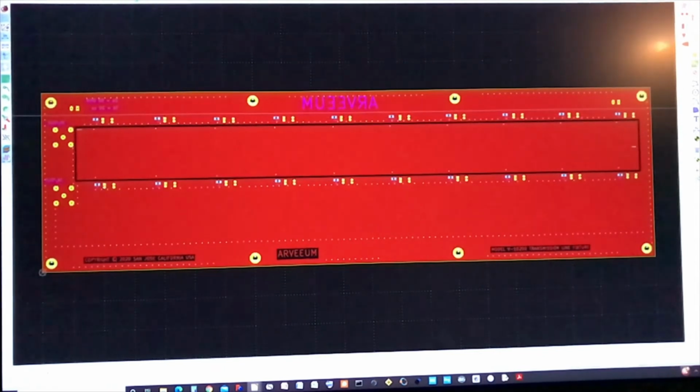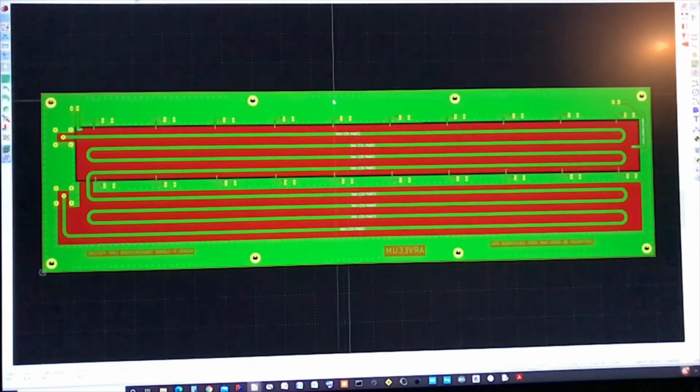And I'll show you that there is a connection right here. You can see there's a via, there is a trace, and it goes to the capacitor and then to the switch and then to ground. So this is so that one can simulate the location of these return current path capacitors along the board and see what makes a difference, just as an empirical way of doing it.